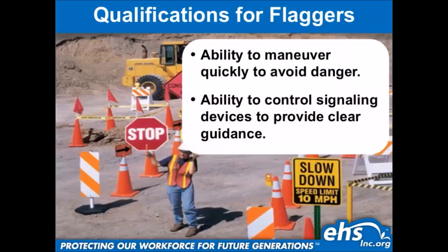Qualifications for flaggers: they have to have the ability to maneuver quickly to avoid danger. That means where you're placing these flaggers matters, right? If you have them right next to a wall where it'll be difficult to scale and climb, and a vehicle is veering in their direction, they've got nowhere to run, right? So they have to have an easy escape. They should never be stationed on a traffic island in the center of the roadway, right? Because if the vehicle's heading towards them, all they could do is run into traffic. So where these flaggers are stationed matters.